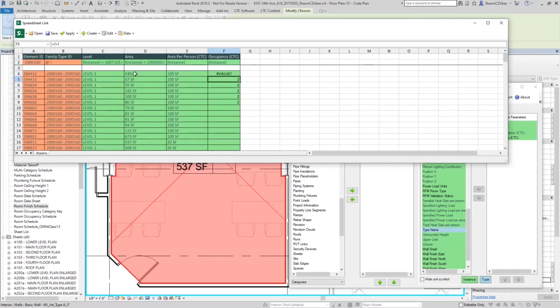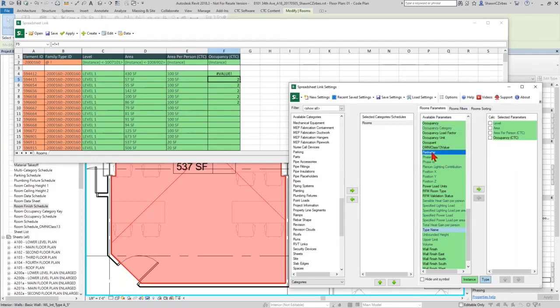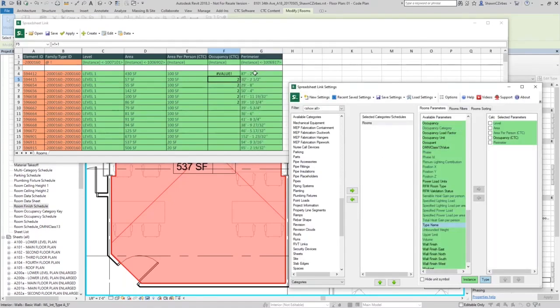Now, because I'm using imperial measurements, I've got square feet out here. In many of your plans, you're probably going to have square meters. And it might be m squared, it might be m to the power of 2 or whatever it writes out there when you export the data, but it's probably going to have units of measure on it. And if it does, it makes it real tricky to go through and do calculations. I mean, this one I could probably trim off 3 characters from the right side and be no problem. Here in the US, when we're using imperial properties, it gets even more tricky when you have feet and inches involved, right? Try and write the strip formula for this. I've done it. It's 1.5 miles long. It's not fun, and it's not easy to debug and troubleshoot later. So I try not to use this.